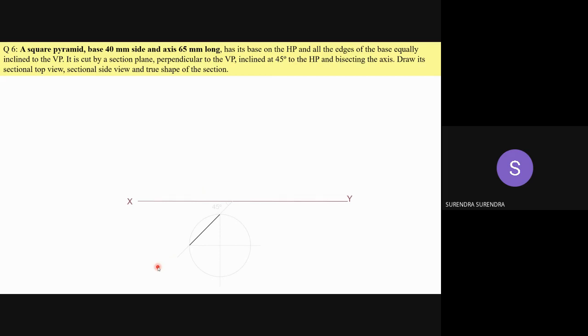One more way of constructing a square. If you are using the drafter, you can use the two perpendicular scale and complete the construction. If you are not using the drafter, draw a horizontal line and a vertical line from the two endpoints, which means the two diagonals, and identify the intersection of the diagonals. Now, with this point as the center, complete the circle.